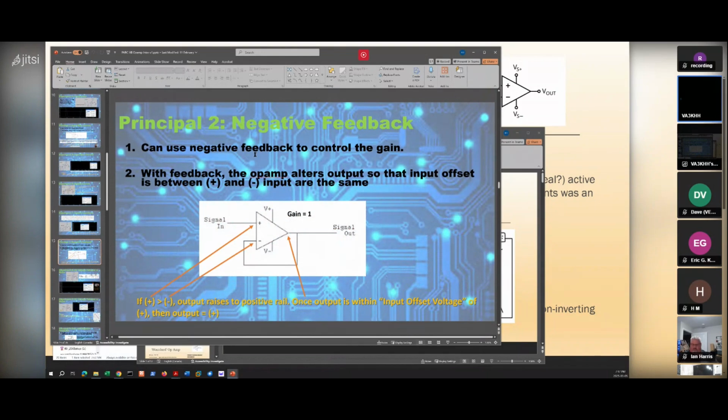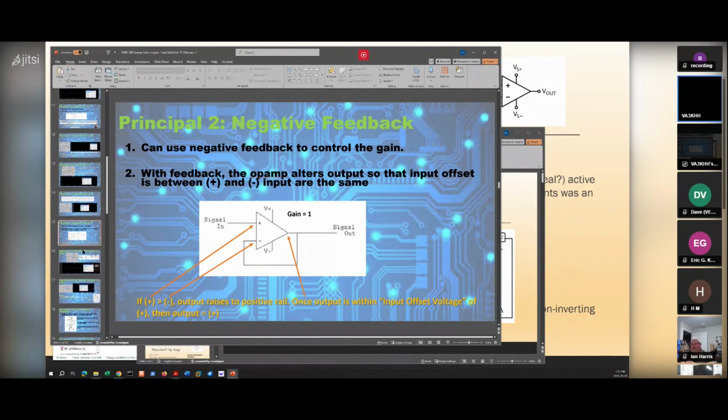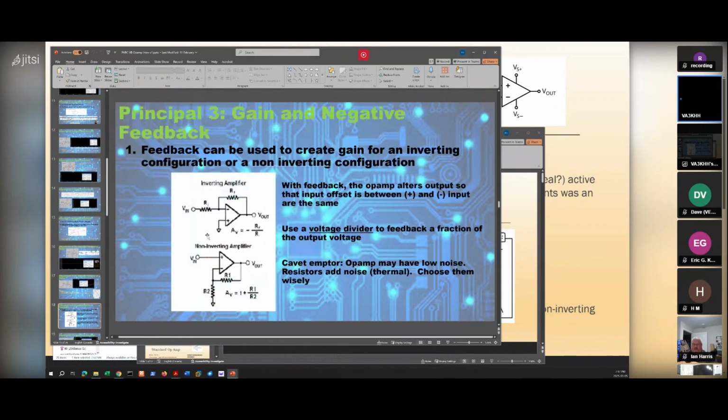And so this is part of controlling the circuit by external components, or in this case, no external components. If you bring a voltage on the signal input here, and this is the non-inverting input, then the output will go where it has to go to keep the differential voltage minimal, or ideally 0, which means that this output voltage is going to be the same as the input voltage because it's non-inverting. So that's a standard voltage follower. And then you've got an inverting amp and a non-inverting amp.